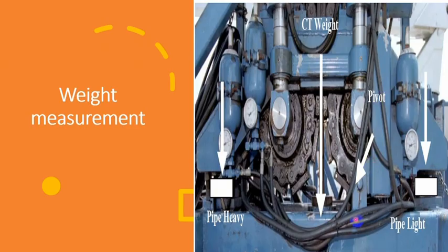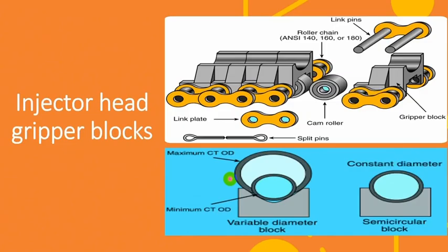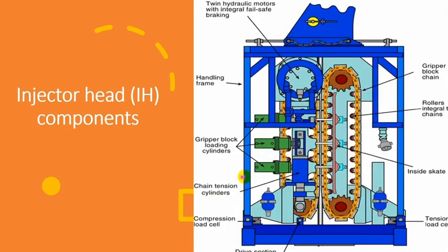This pivot point makes the injector rest with its weight on these two load cells. One will measure the tension and the other will measure compression. As you can see from here, this is a compression load cell and a tension load cell with the fulcrum point here. So your injector in cyan color will rest on this load cell and this load cell.